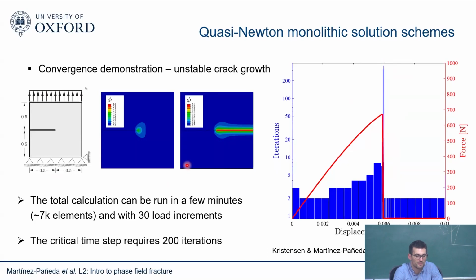And you may wonder, how can this be? This is mode 1 fracture of a linear elastic material. Fracture should be completely unstable. You should lose load-carrying capacity. It should not be a progressive failure. But you can get that in staggered approaches.